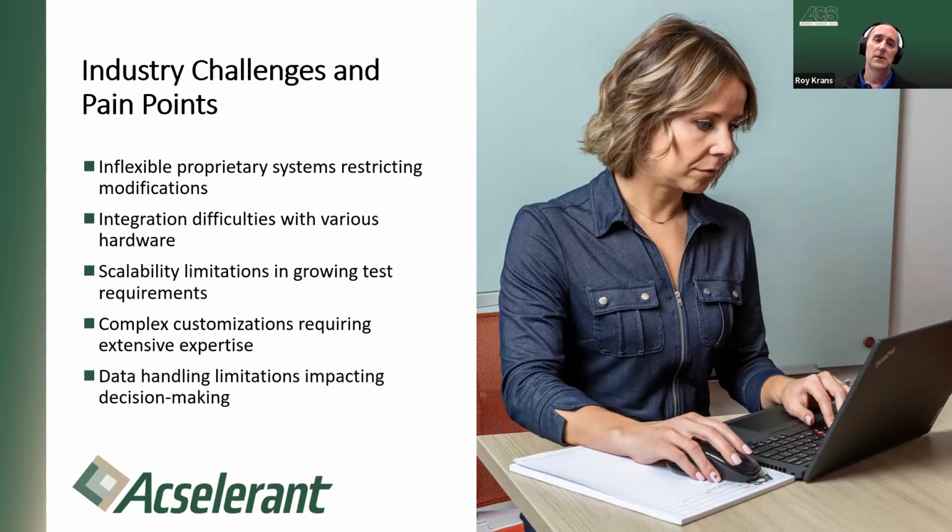Scalability problems. Again, if you need to expand the number of channels, the number of calculations, the number of test scripts, anything like that, how can you do that? We haven't built into it any inherent limitations. Your primary limitation is just computational horsepower as you build more systems. Adding additional I/O, since the majority of everything we do is configuration based, you simply add the I/O, update the configuration to include the new I/O, and now you're ready to go.